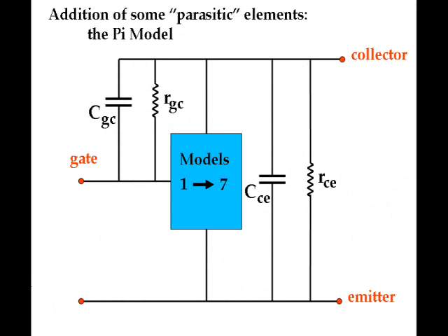Any of the equivalent circuit versions of the basic charge control device can be augmented by numerous parasitic elements that also may have different operating point dependencies in the different devices. The most important of these are usually non-zero admittances from the collector to the gate and to the emitter, which led the augmented equivalent circuit to be known as the pi model. Addition of CGC, represented by the base collector capacitance Cμ of a BJT, is treated by use of the extra element theorem in Chapter 6.